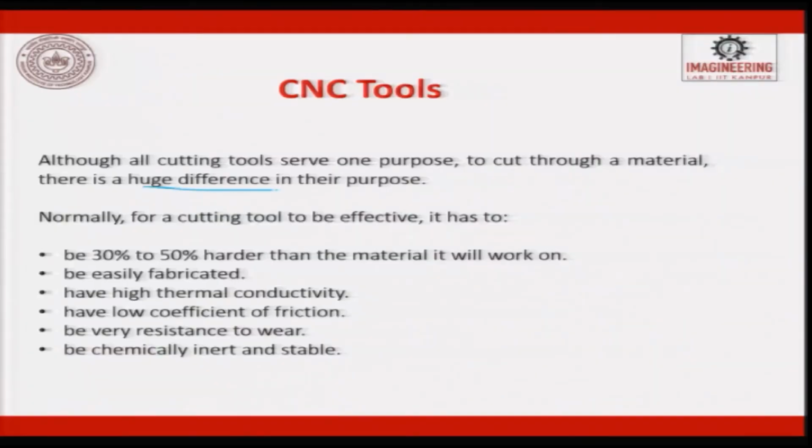If there is going to be a huge depth of cut, then there has to be a change in the angle. If there is a huge depth of cut and it is a non-conducting material, the tool material has to take the heat, so it has to be made out of ceramics. So, you see there are huge differences in their purpose.